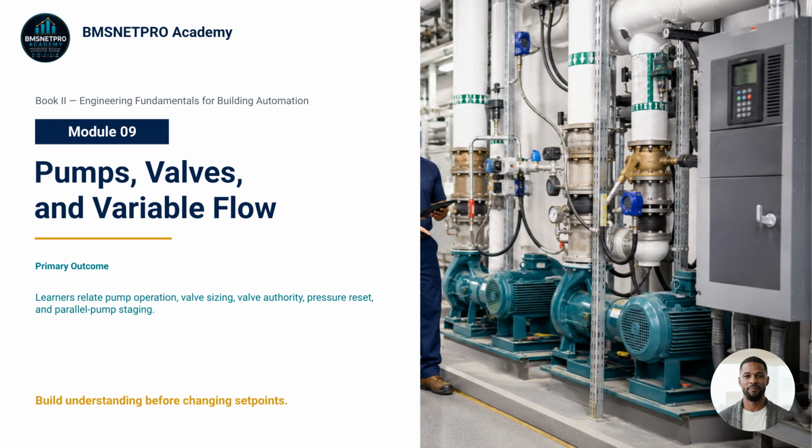Welcome to Module 9A, Pumps, Valves, and Variable Flow. In this module, we move deeper into hydronic systems and focus on the components that determine where the water actually goes. A pump does not magically create flow through every coil. It creates head. The valves, piping, strainers, coils, and branches determine how that head is used.